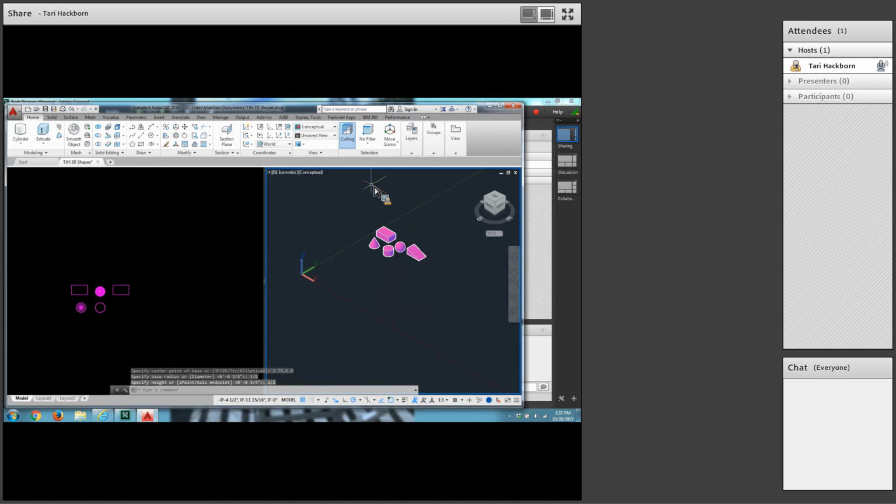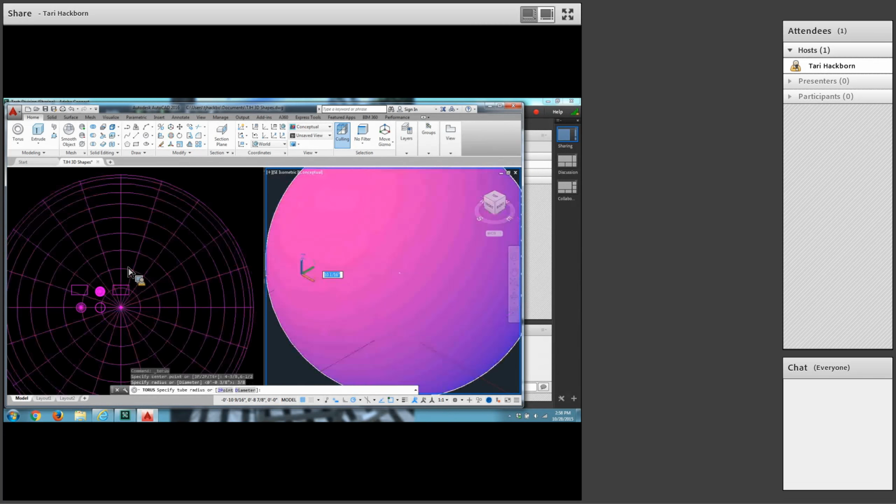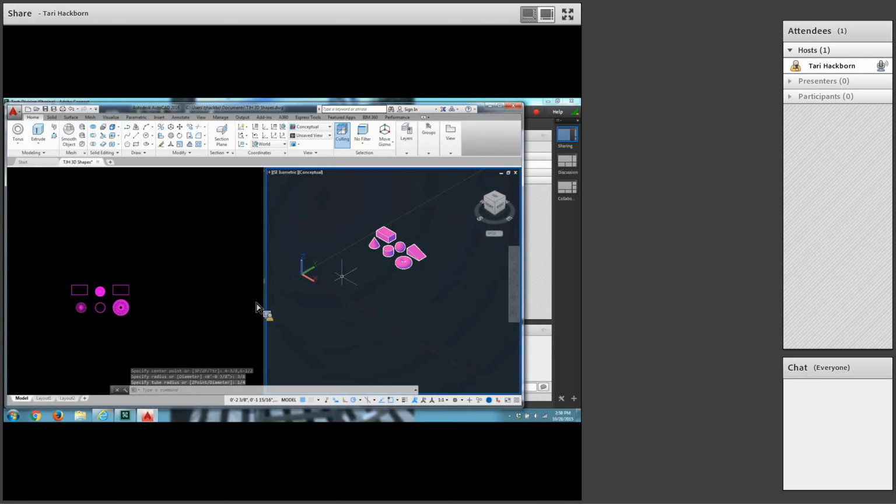Okay. The torus, that might be our last primitive. The torus begins at 4 3/8, 6.5. That's how I'd type it in. All right, what else does it tell me about the torus? There is a radius of 3/8. And an inside radius of 1/4 inch. There you go. Looks like a donut, doesn't it?